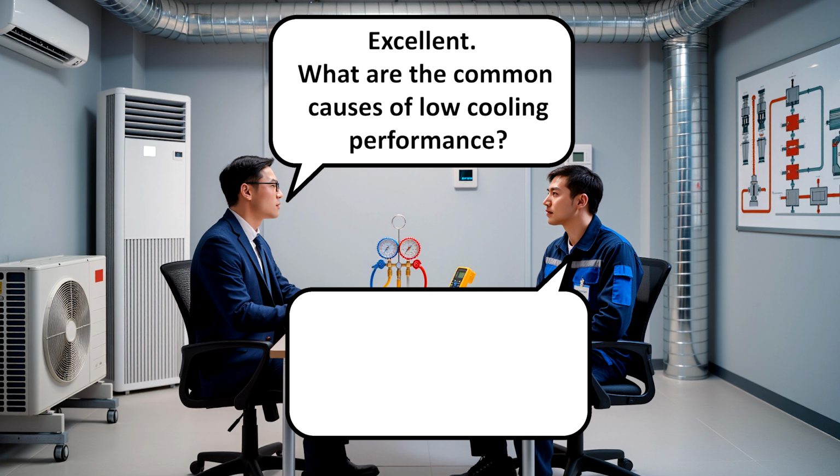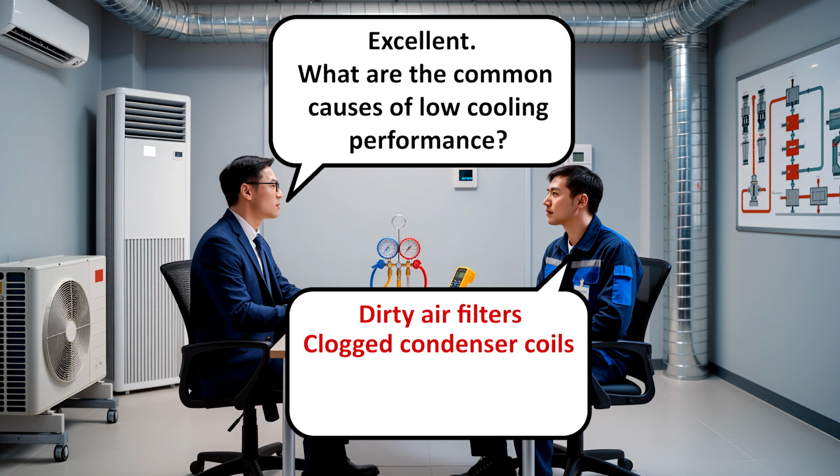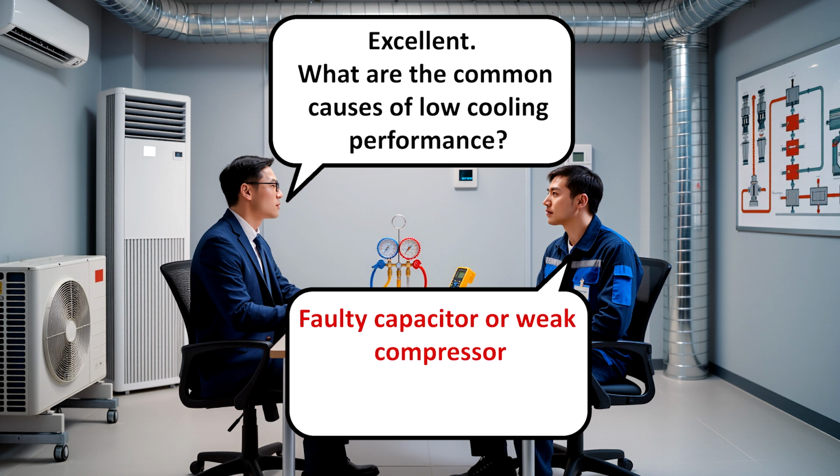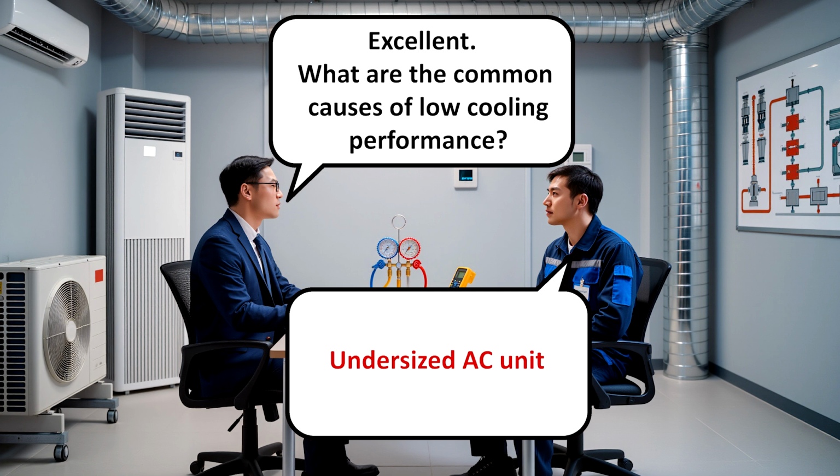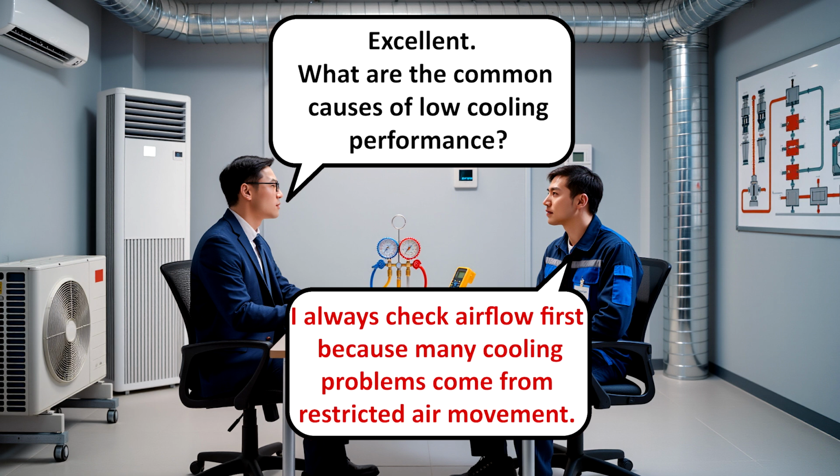Excellent. What are the common causes of low cooling performance? Usually the main causes are dirty air filters, clogged condenser coils, low refrigerant charge, faulty capacitor or weak compressor, improper airflow due to blower issues, undersized AC unit. I always check airflow first because many cooling problems come from restricted air movement.